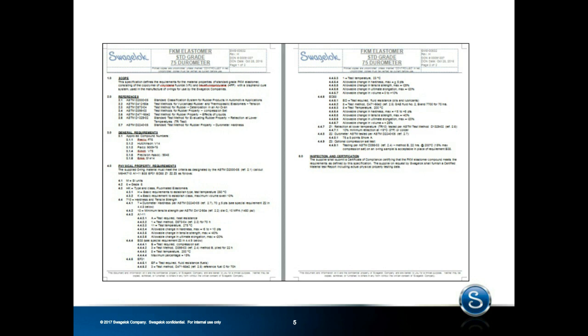So what I do to specify is I call out the O-ring compounder and their recipe. That way I know specifically what the expected properties are for that seal material. So if you're in a situation where you're specifying elastomer seals for use in your processes, you need to make sure that you're asking your sourcing folks to purchase those seals to a material specification. And assuming you're the one writing that material specification, it's really important for you to define which O-ring manufacturer and compound is acceptable for use in your process.